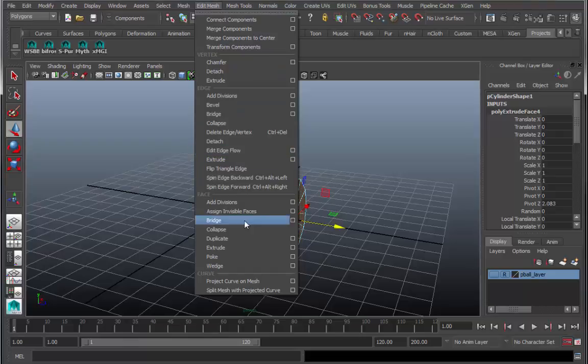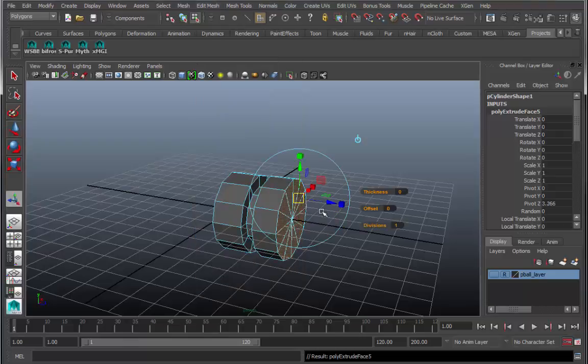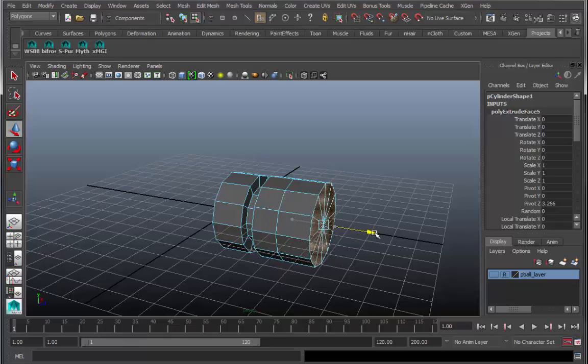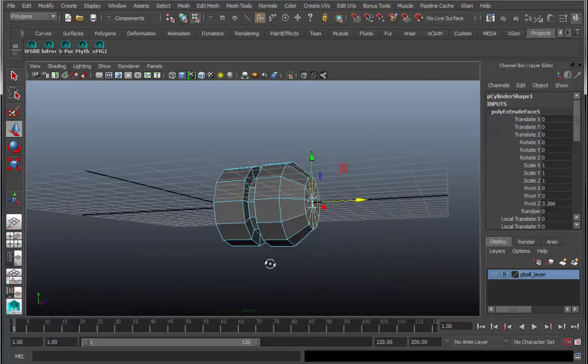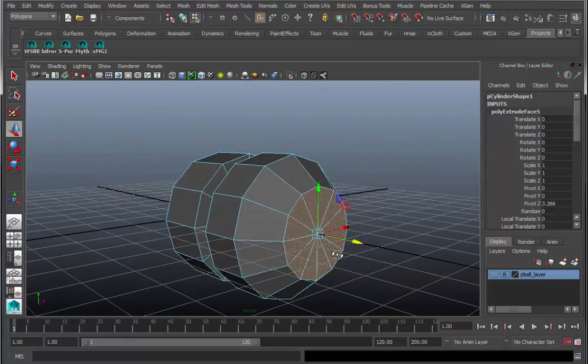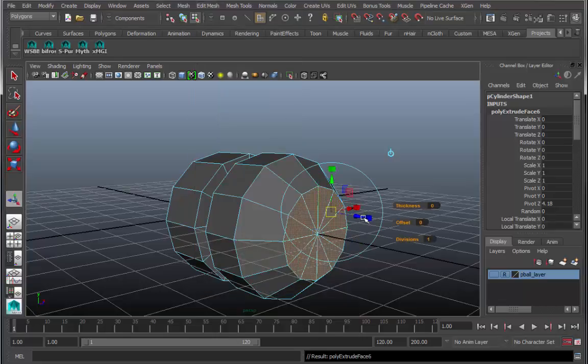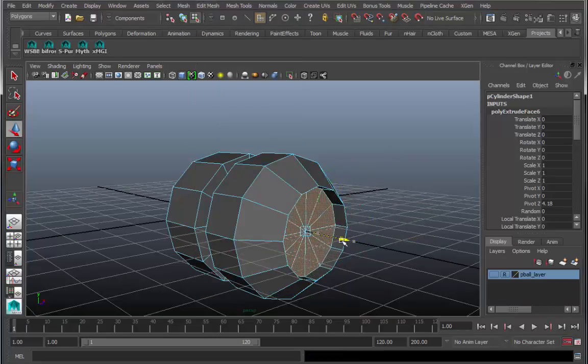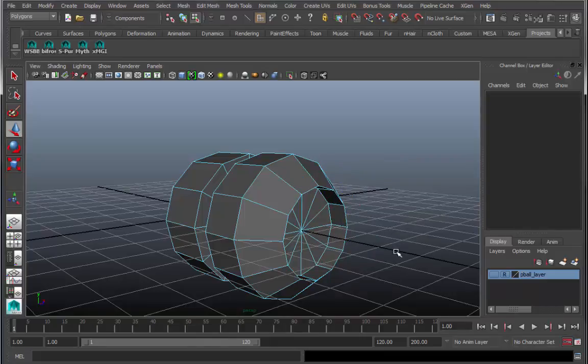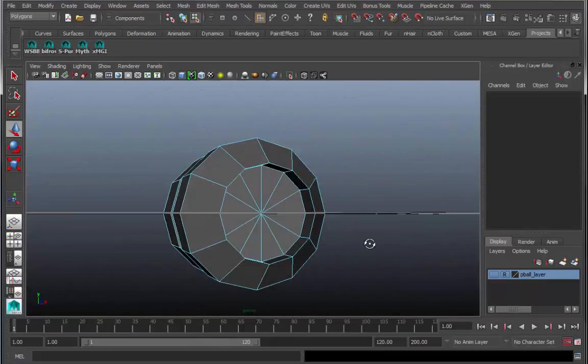And I want to extrude again, and this is going to be a combination of extrusion out first, and then I'm going to pop immediately to the scale tool and scale it down, creating this kind of strange little doorknob. I'm going to push it in again. This bevel, as it were. And that's a combination of both extrusion and scaling, translation after the extrusion and then scaling. And I'm going to do it one more time. Only this time I'm actually going to push it in just a bit, like so. So now we got that cool little doorknob look.